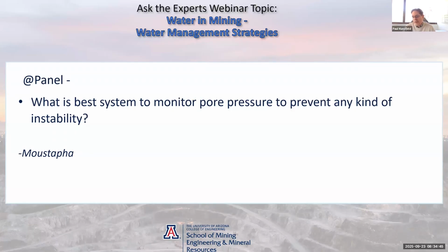And they also provide you with good data in relatively short spaces of time versus a conventional, for example, open monitoring PVC completed hole, which may take weeks or months in very low permeability environments to stabilize, and it will only give you a phreatic level, whereas vibrating wire sensors will give you pore pressures and will give you differences in hydraulic gradients across structures, which can identify areas of pit instability. So generally, that's the best method.